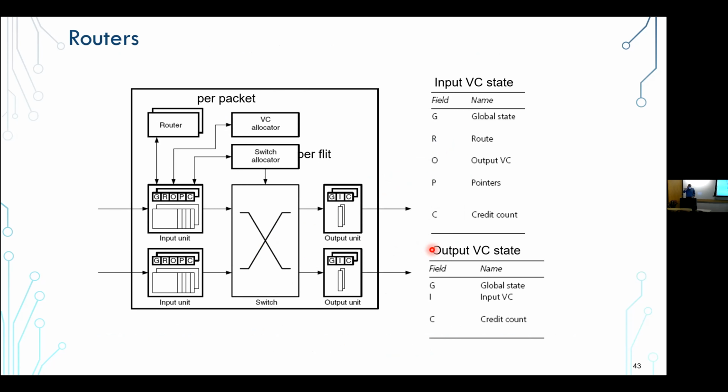Okay, so that's a little bit about the channels and the options you have there. I would say that people don't really build equalized links today, especially because it's a risk of this bit error rate and losing the packets. But what people do is look very carefully at what swing you want to have on those wires if you really want to have a low power optimized network on chip, especially for longer routes.